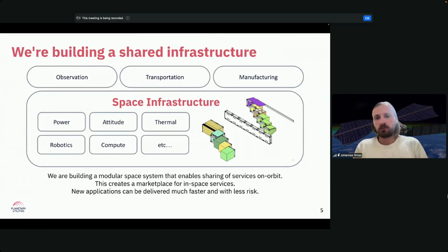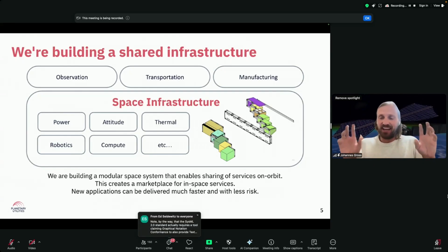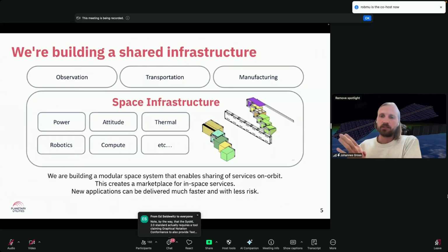To build this space infrastructure, we started out by looking at the engineering environment that we need to actually allow this. I want to make one example. The last instrument that I built for the International Space Station was called EMIT. It's a spectrometer instrument. The time from unloading the instrument from the payload bay of the Dragon capsule to the plug-in into the American External Payload Adapter was actually 6 hours because of the robotic arm, which was from Canada, and we didn't have a closer interface. These 6 hours were actually the driving use case for our thermal system.